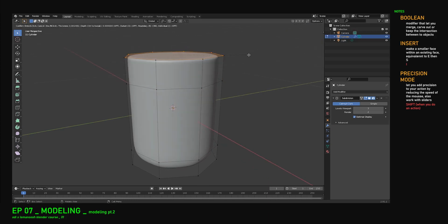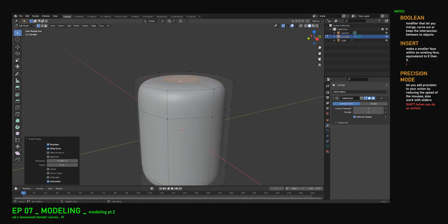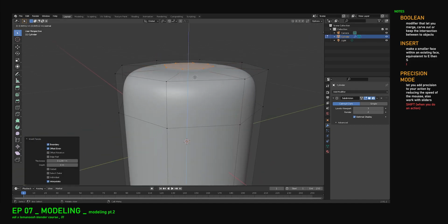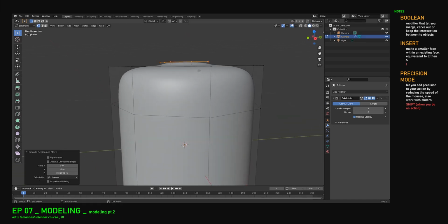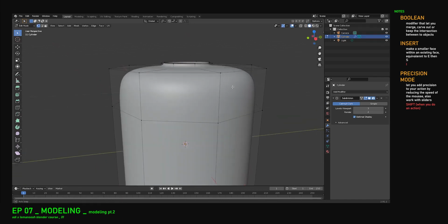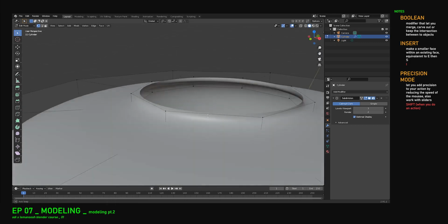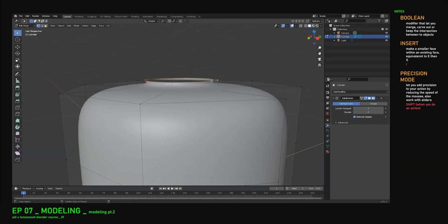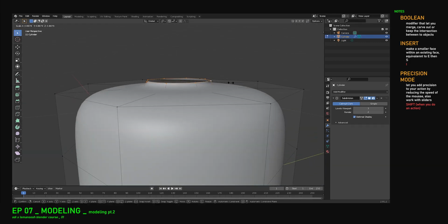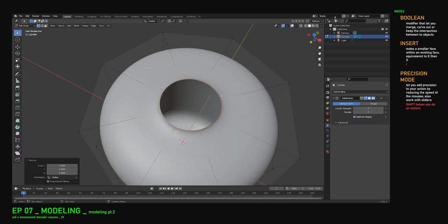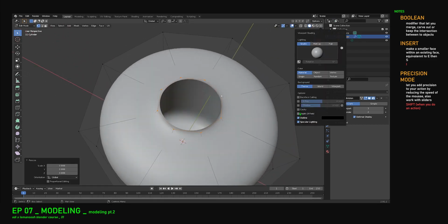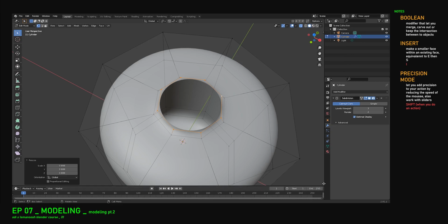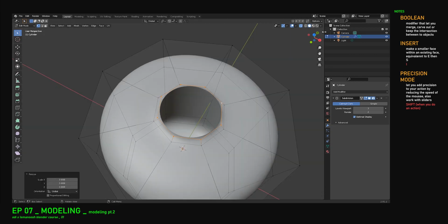We just have to do an inset with I. We scale it down, and we can extrude just a bit. And what you can do here is remove the face so that you would have a super sharp edge, and then if we have to build something in between in there, it's not a problem. Let me just add the X-ray, and let's remove the timeline actually.